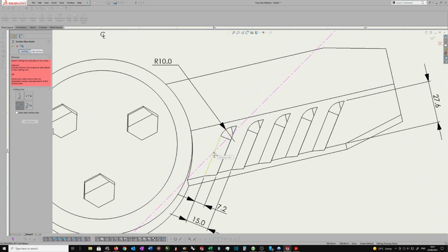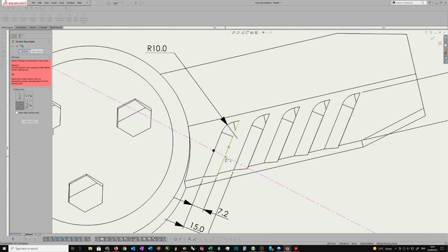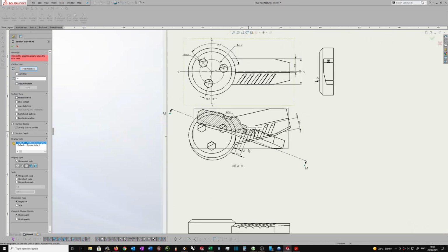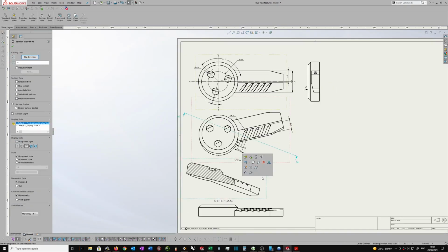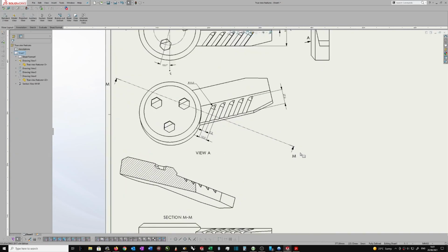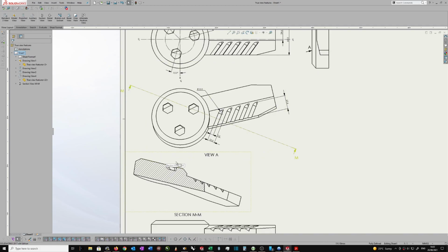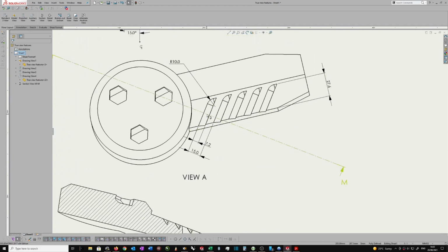So I'm going to go like this, and you'll see it doesn't really want to grab anything. It won't give me a perpendicular sign, and it must be perpendicular. So I'm going to just place it, say that's okay, and then go out. Right. And there are two things about this. One is I want this line to be much shorter because I just need this little piece here. And two is I need to make sure that that line is perpendicular to that line or to that line.